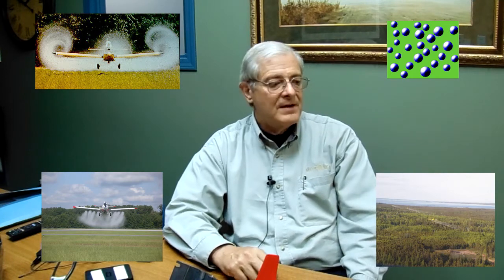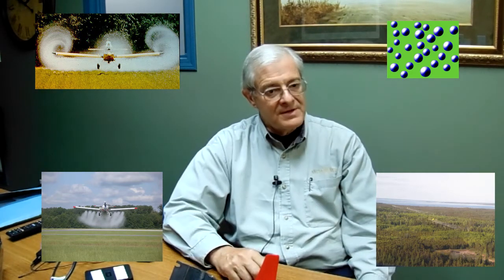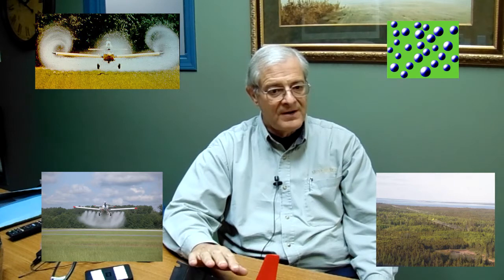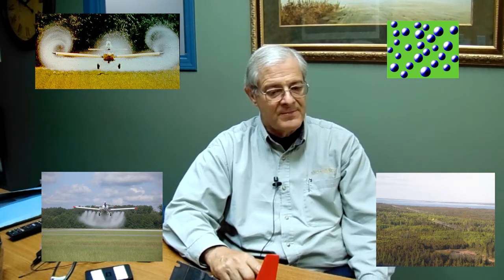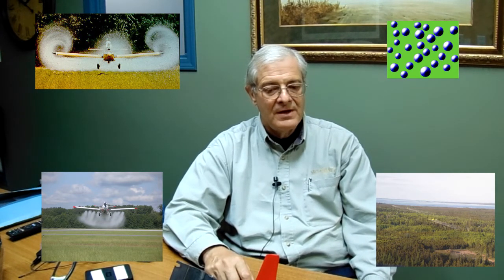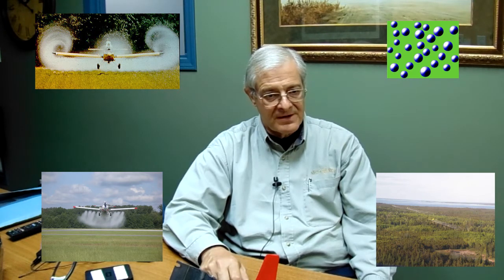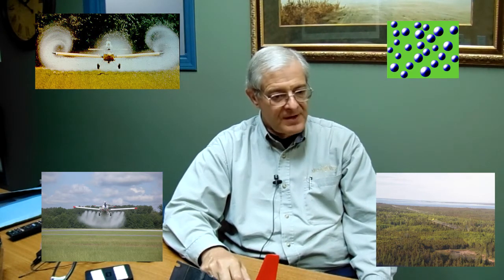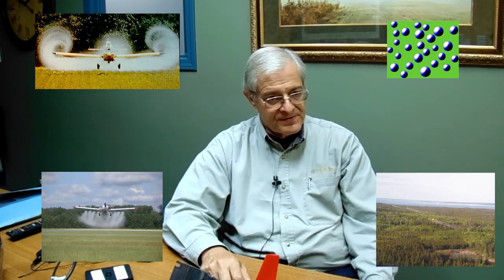In forestry, very often we're not so concerned about drift because we're spraying enormous areas with small droplets, typically of an ultra-low volume product, which is formulated in an oil and is not volatile. And in forestry, it's quite normal to go out beyond the 2/3 of span and to accept that there will be some product thrown into the vortices and potentially drift a bit. But then again, those aircraft are operating at much wider track spacings than is the case in agriculture. So very often you will have a different setup between forestry and agriculture.